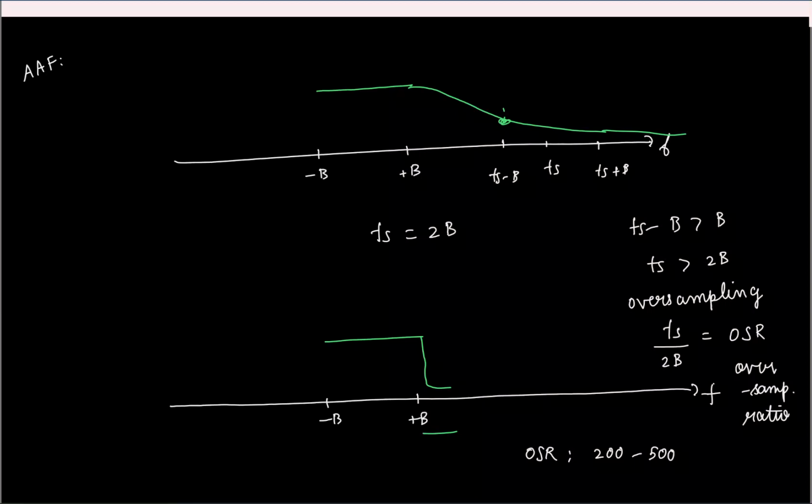Great. So bottom line, before sampling you have an anti-alias filter, and to make sure the design of the filter becomes practically possible, you make sure you oversample beyond the Nyquist recommended sampling rate. Great. So now we have seen sampling, that is how we can convert continuous to discrete time. Let's quickly look at the inverse operation also, how you can reconstruct from the samples.